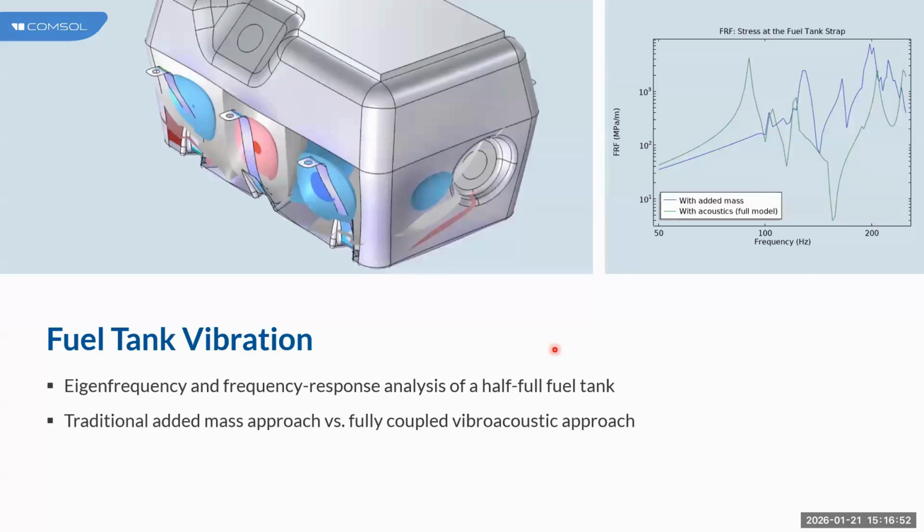So moving ahead, next we have the example of fuel tank vibration. This is another model that analyzes the frequency response of a fuel tank partially filled with fluid, again in vibroacoustics. Here the tank is subjected to a vertical acceleration, and two modeling methods are considered to represent the fluid in the tank.